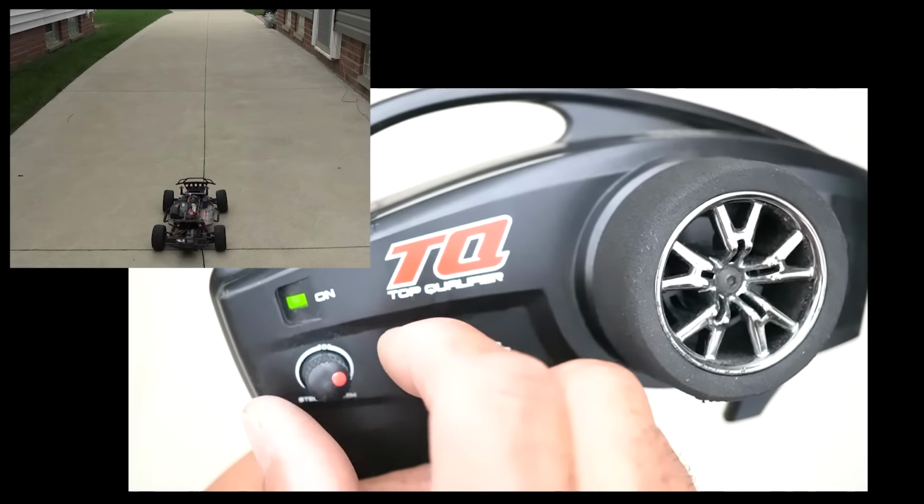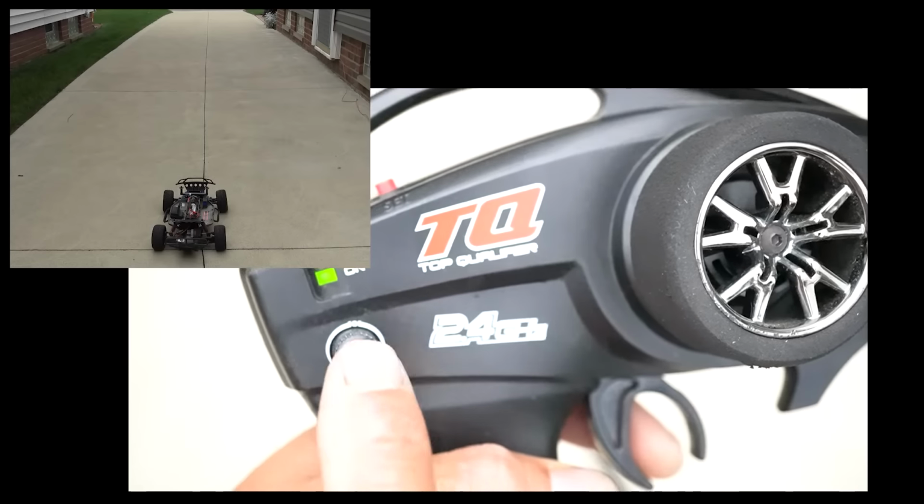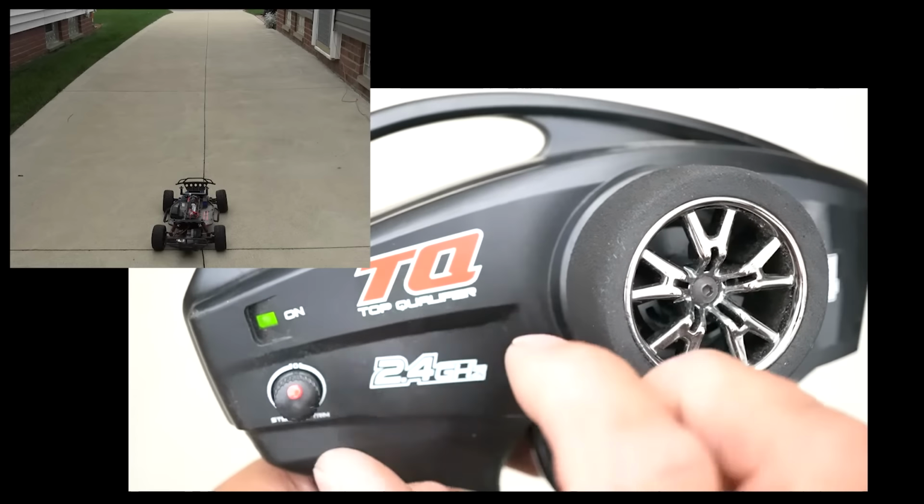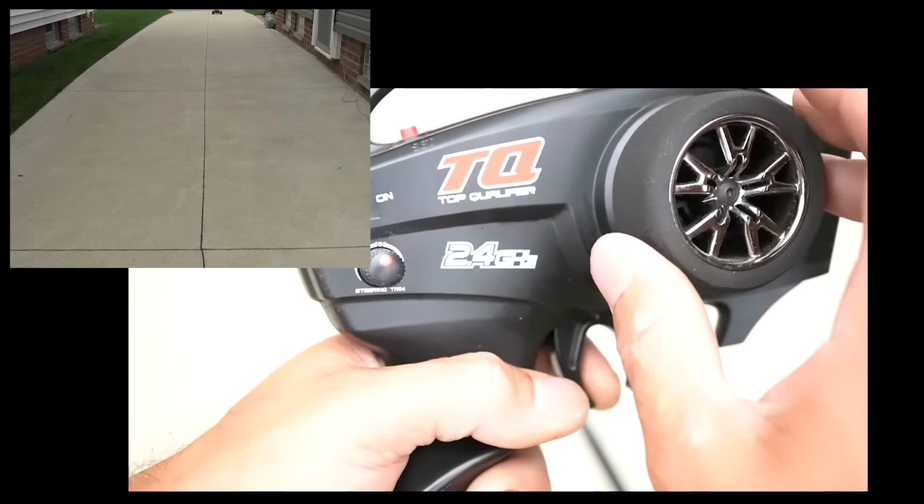Now here's where the lesson comes into play. Our long term follows our short term, okay? So if I start driving down the road, from the factory, this vehicle should go straight, but it doesn't. So my short term has to hold the wheel. I'm holding my short term or making minor corrections all the time to my short term. And I get tired of doing this. I don't want to have to do this all the time. It makes the job hard for me, right?